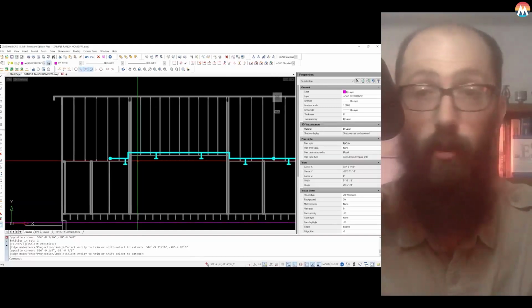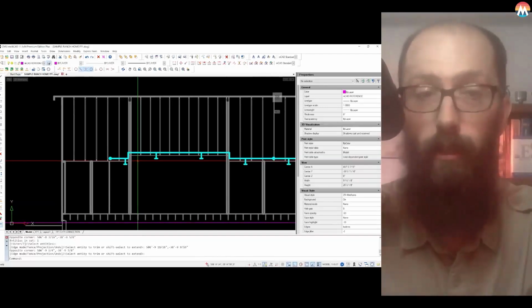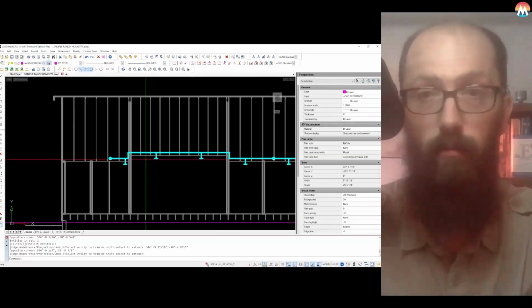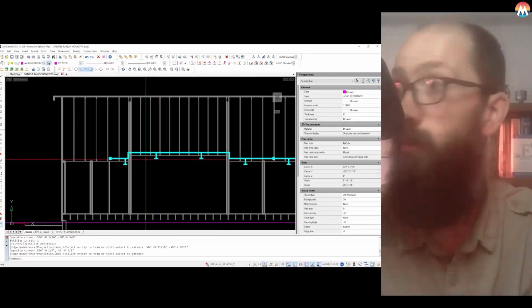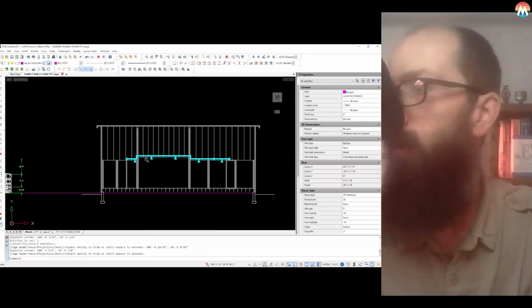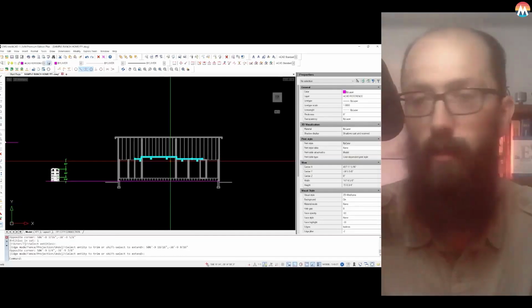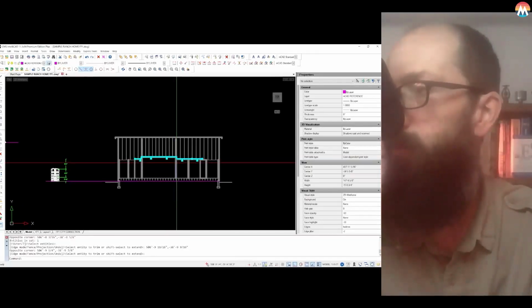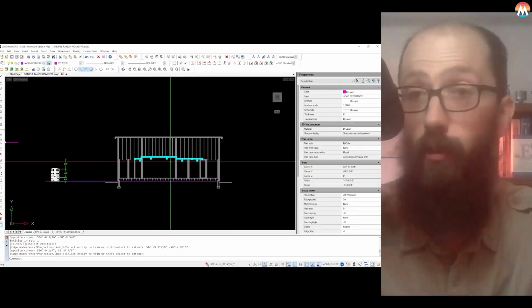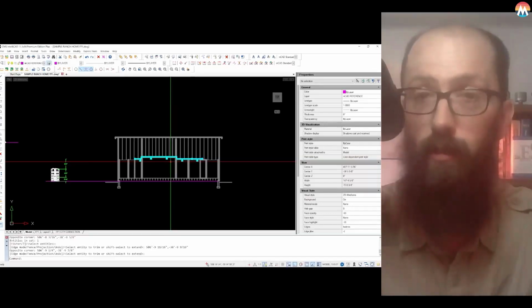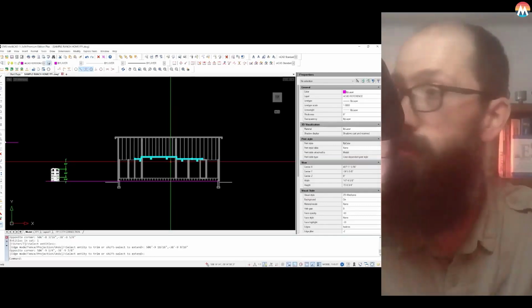But, you know, they're really trying to make it comparable to a residential house plumbing drawing. You don't need to lay out the piping on that. You just show where the fixtures are. But in a jurisdiction that wants you to have something like this, this is how you would provide it. And when we get into 13R systems and 13 systems, it's a requirement to have a section.